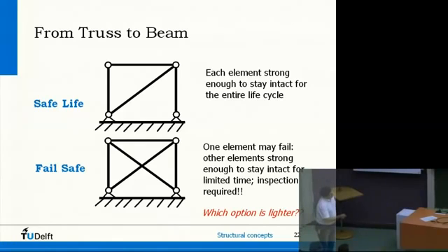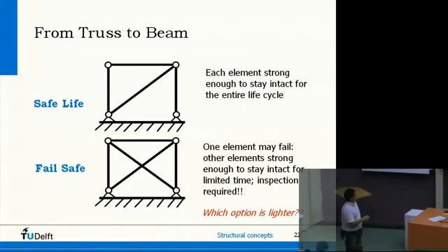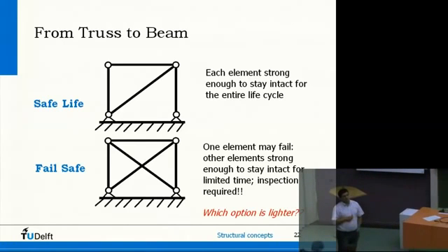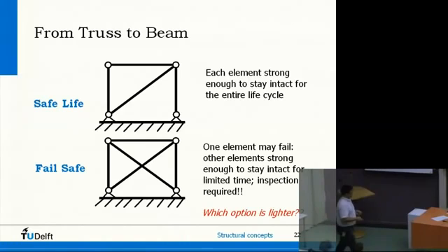Most of the structures nowadays are designed with this concept in mind. There are a few items, like undercarriage for instance, that are still designed in a safe life philosophy. You cannot make that redundant. You only have one nose wheel for instance. You are not going to do it twice. Yeah, so there you have differences in design.